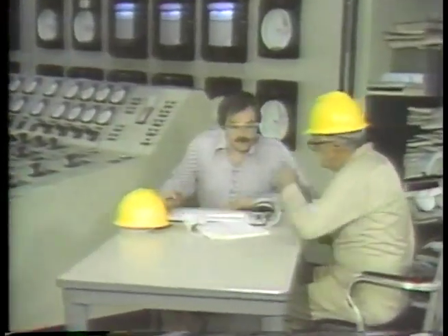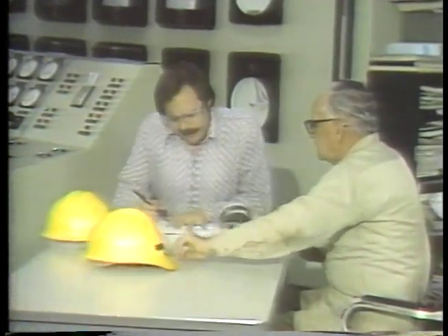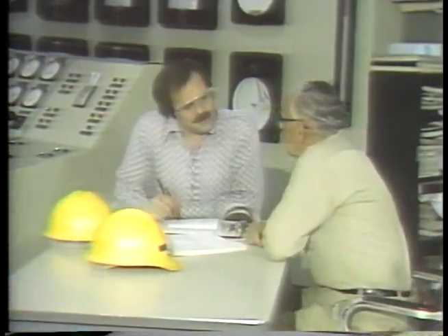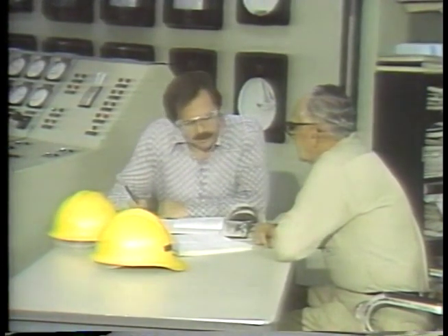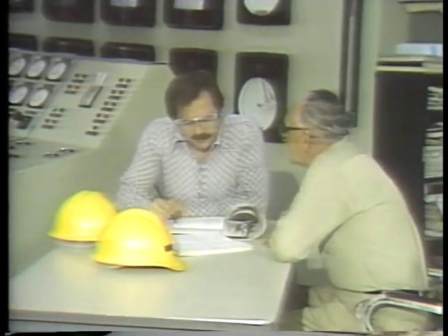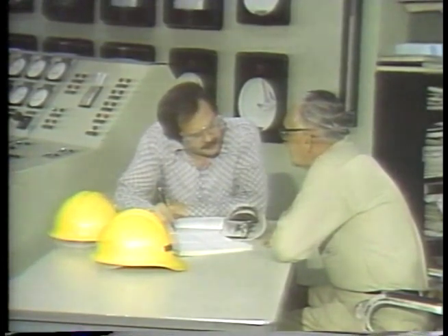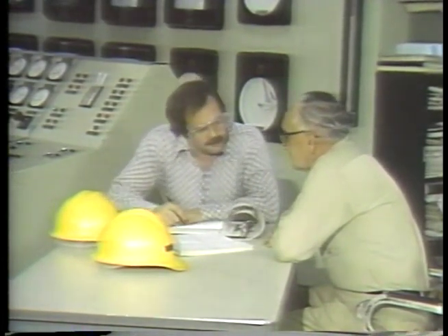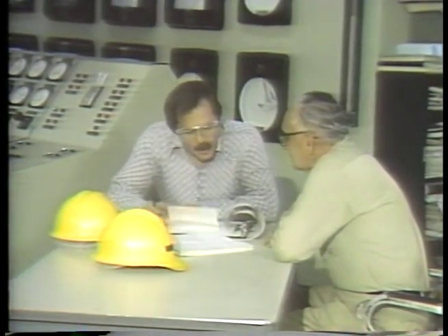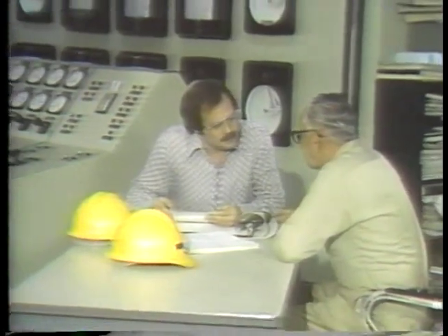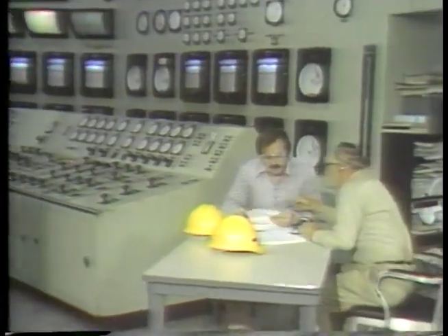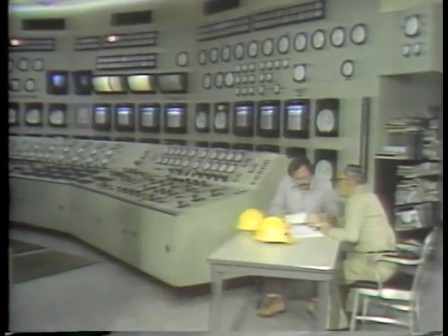Oh, I'm glad you showed up. I need to find out the enthalpy of steam at the outlet of the boiler. And I know that its temperature is 1,000 degrees Fahrenheit and its pressure is 2450 psia, but I can't find it in either Table 1 or Table 2. That's because the process is superheated, so you have to use Table 3. Turn back over to the superheated Table 3.